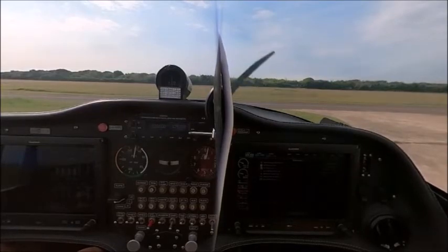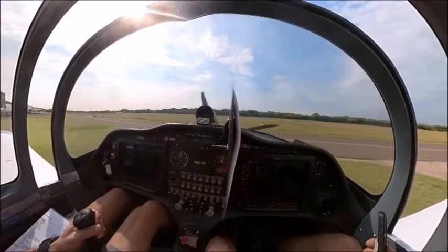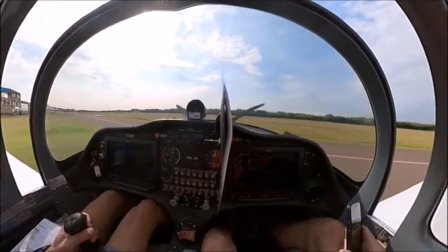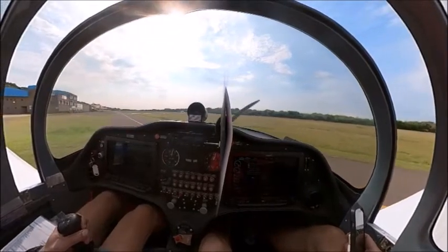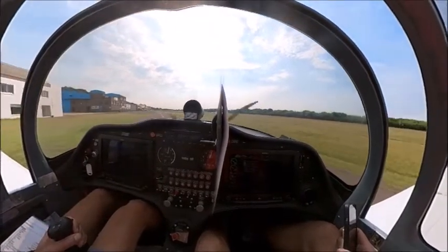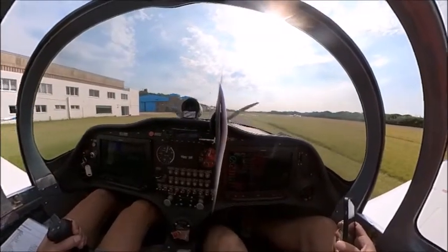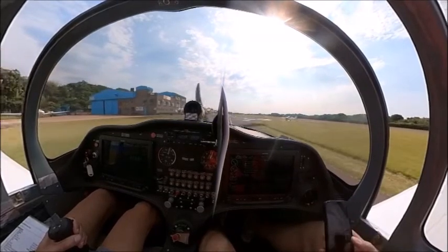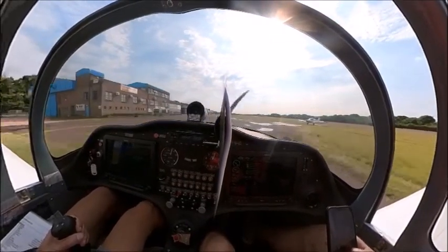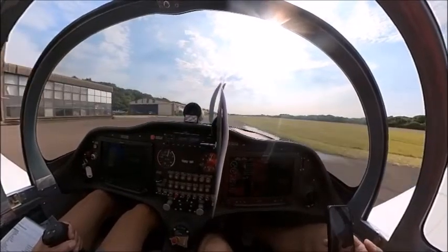So over here, I had to change the QNH setting, so that would indicate 0 feet on the instrument when it's at sea level. Okay, and then you will notice that everything that the air traffic controller would say, I would have to repeat, to make sure that I've heard the instructions correctly and that I'm able to follow the instructions that they need me to follow.